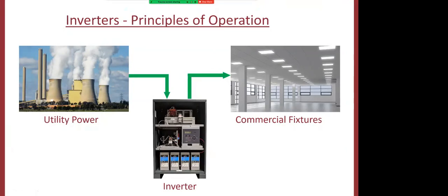One thing you need to note is that in this picture, if maybe a quarter of these fixtures were battery pack fixtures, that would mean that you would physically need to be swapping out battery packs in these fixtures. You would also need to do the monthly and annual testing of these fixtures by going up to each individual fixture. How inverters work, they take those battery packs out of the fixtures and they centralize all of that battery power in one area contained within the inverter itself.